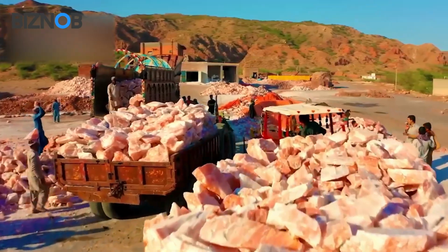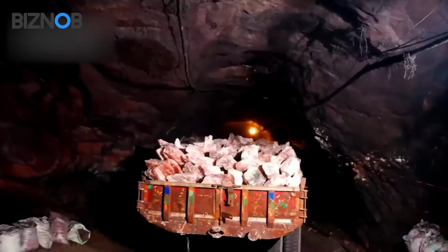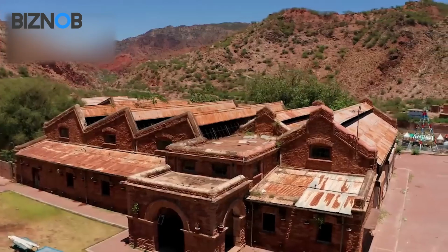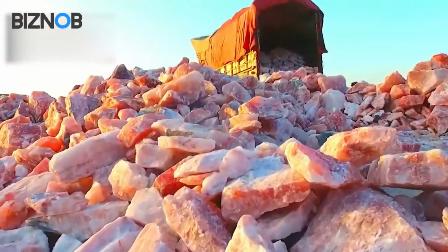Ventilation involves the use of fans, ducts, and air shafts to circulate air throughout the mine. This system not only provides fresh air but also helps control the temperature and humidity levels, creating a comfortable and safe working environment.